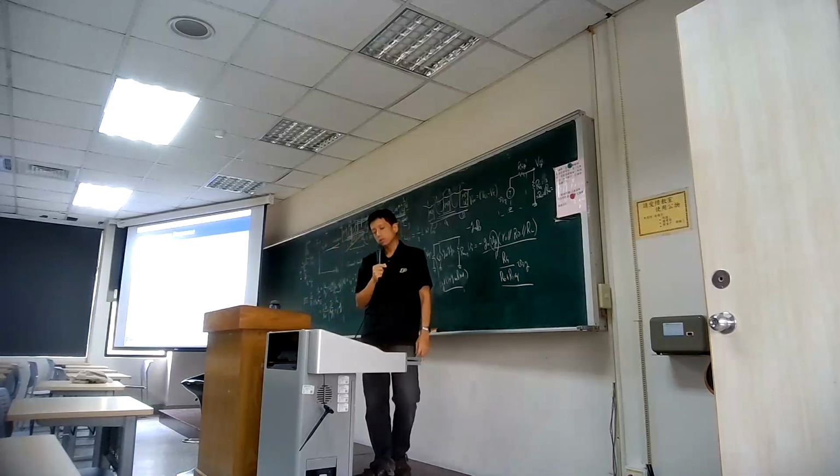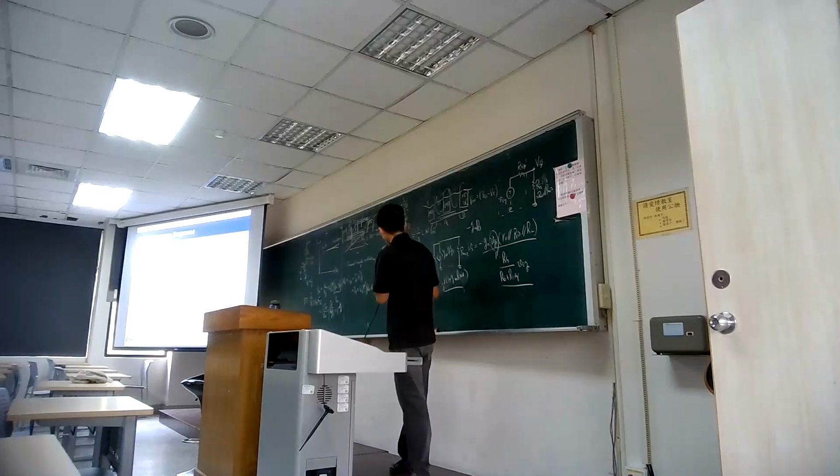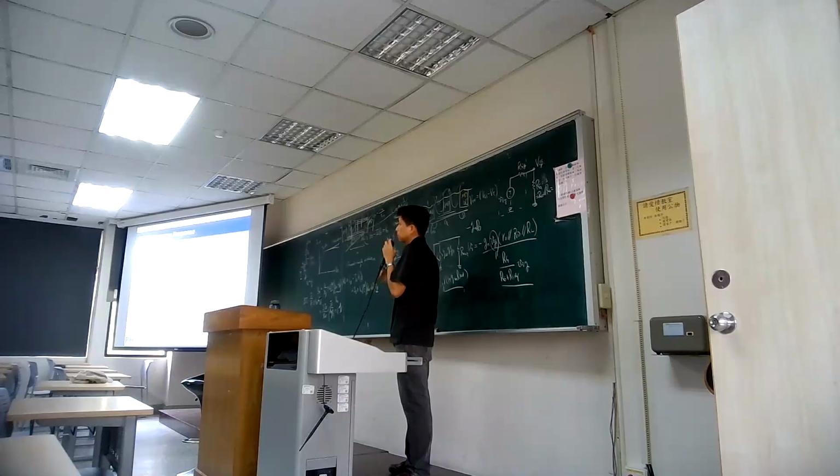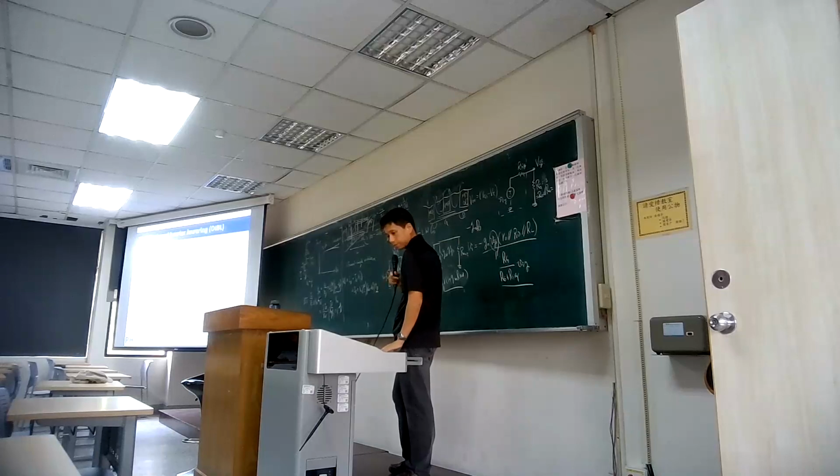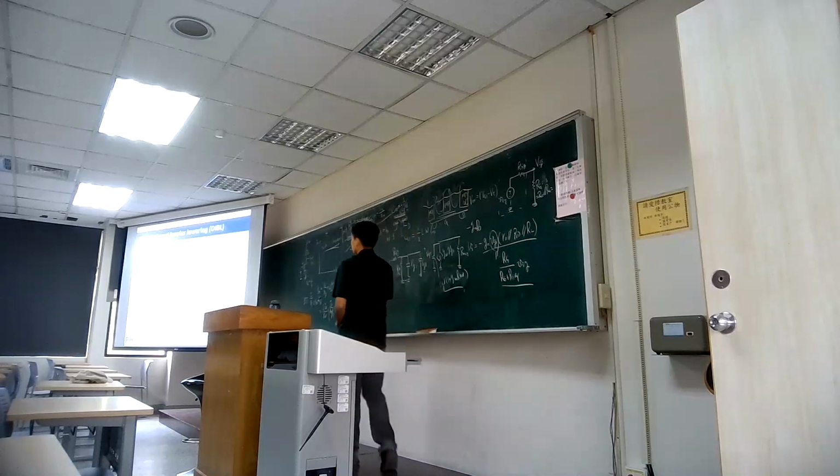So if you get a higher resistance, you get a lower frequency response. Okay. So how do we actually reduce the capacitance in the transistor? You need to consider replacing with low-K material or even with air. Okay.